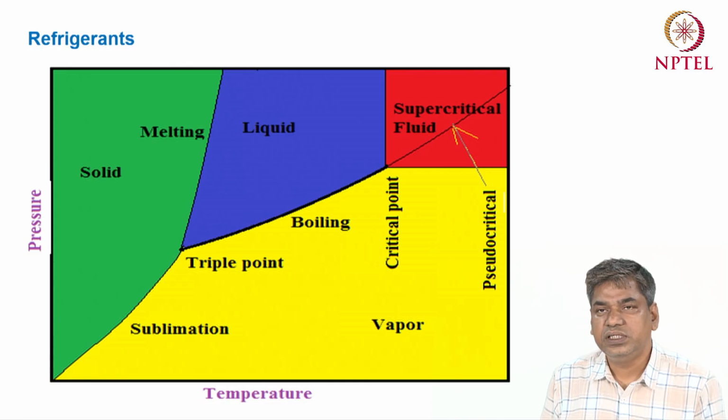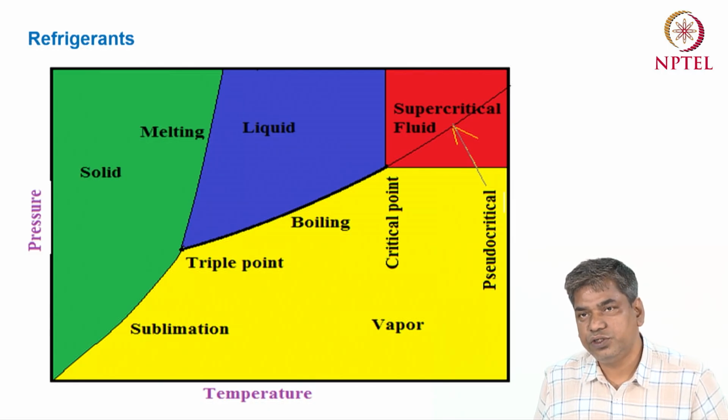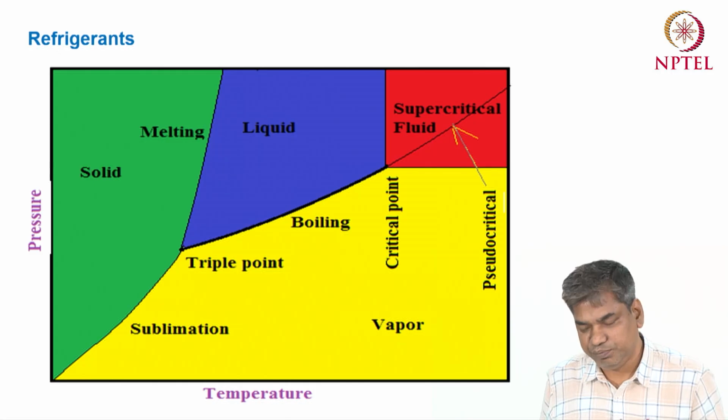So the condition should be that the evaporator temperature should be higher than the normal boiling point temperature and also higher than the triple point temperature.